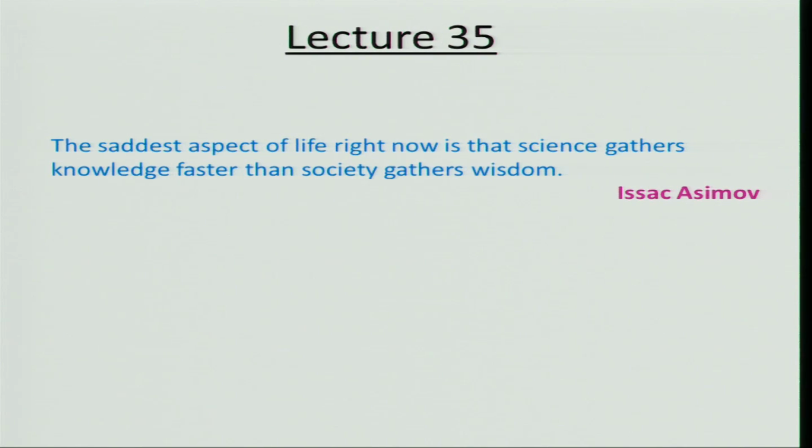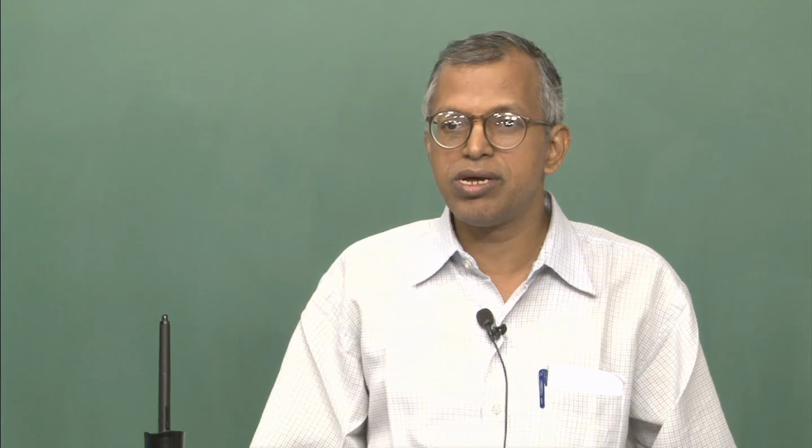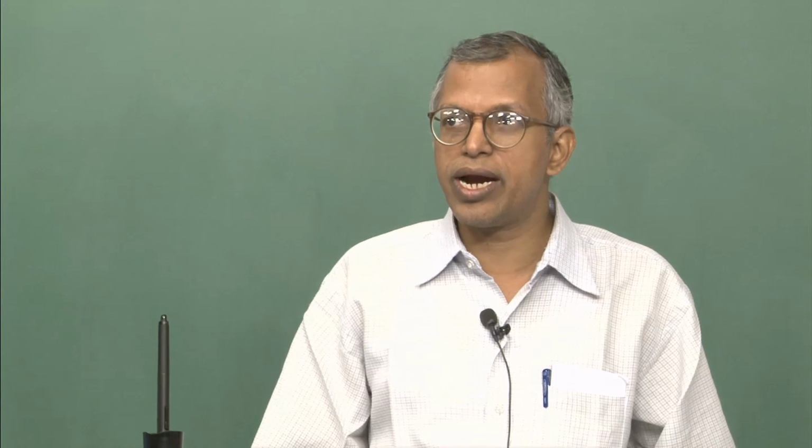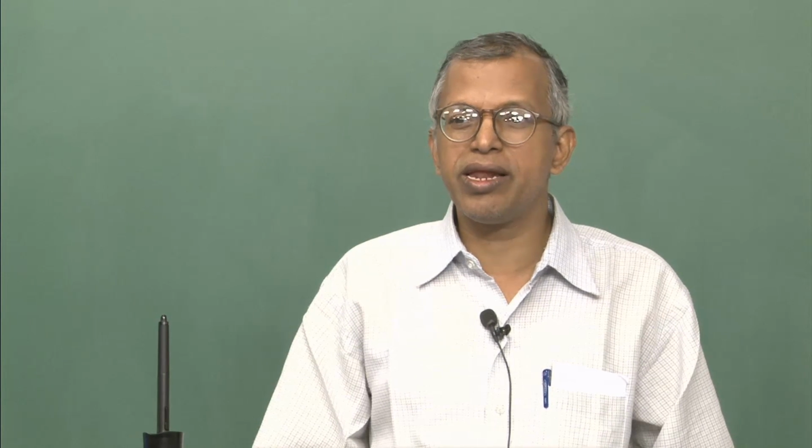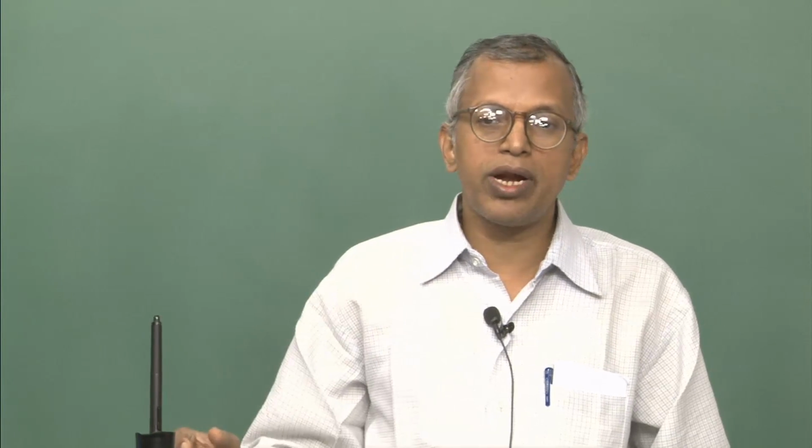And let us recall what we learned in the last lecture. Last lecture, basically, we looked at the analysis of turbofan engines, right, and then we looked at the parametric characteristics of the turbofan engines, and we learnt that the bypass ratio and the fan pressure ratio, compressor pressure ratio play a very important role, and by enhancing the bypass ratio we can reduce the TSFC.